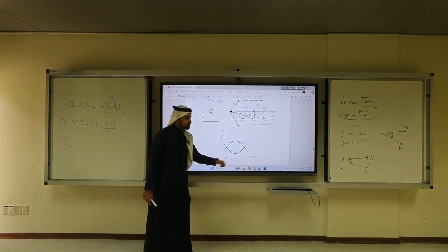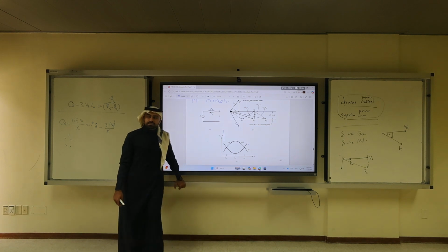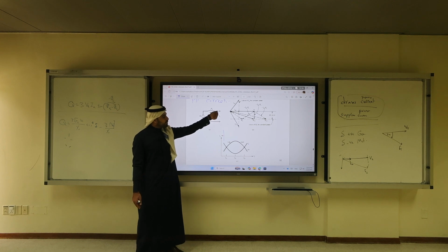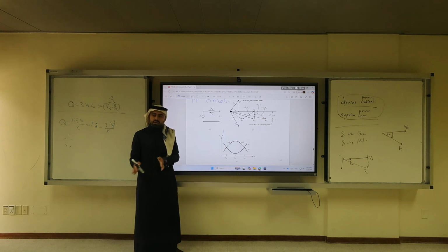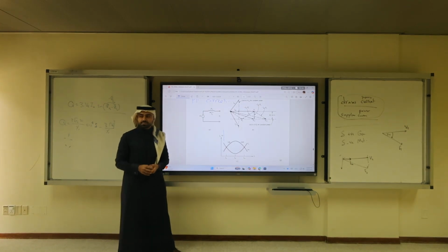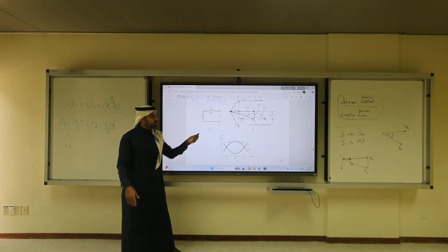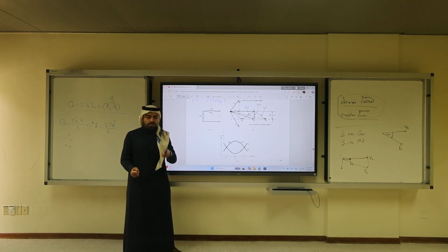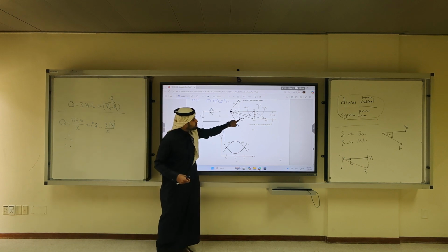EF is the same as IF. Doctor, when you say power factor correction, do you mean for the system or for the motor? No, the power factor of the terminal for the system, not the motor. I mean the power factor between VT and IA for the bus, for the terminal. When I connect a motor to the terminal, I can change the power factor of this bus by changing the excitation, but not the power factor of the motor, which is usually 0.8. I'm not using this motor as an actual motor. I'm just using it to control the relationship between IA and VT by changing the field.